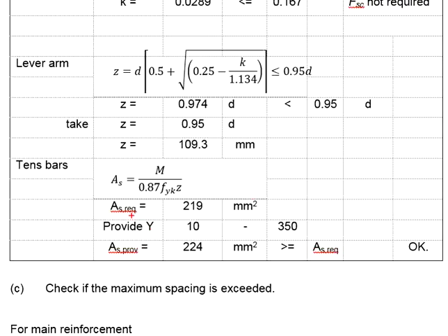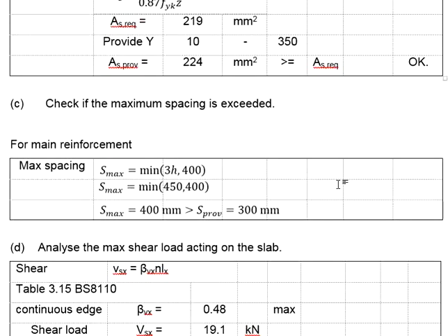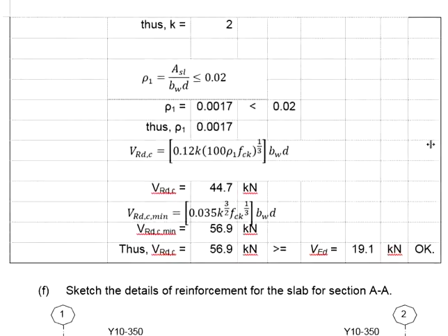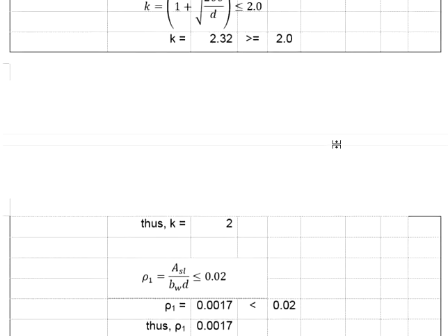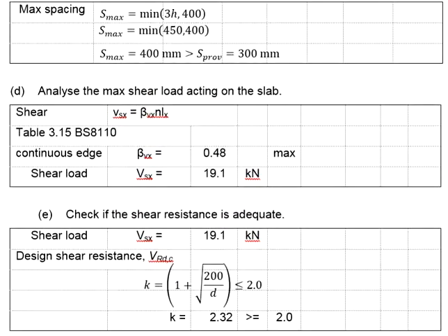After you have decided the amount of reinforcement bar to be provided in the slab, and after you have checked the shear resistance to be adequate, that means you have completed the design for the ultimate limit state, particularly for the moment and shear resistance. Our next step will go for serviceability requirements.